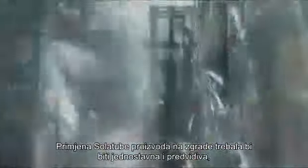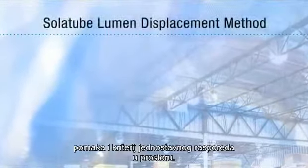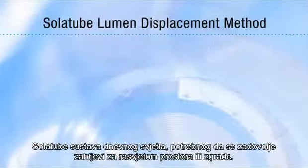These tools include easy estimating guidelines, lighting design data files, and drawings and specifications. Let's start with two easy estimating tools, the Solatube Lumen Displacement Method and the Simple Spacing Criteria. Using these basic back-of-the-envelope approaches, a designer can very quickly establish an initial estimate of the quantity of Solatube daylighting systems necessary to meet the lighting requirements of a space or building.